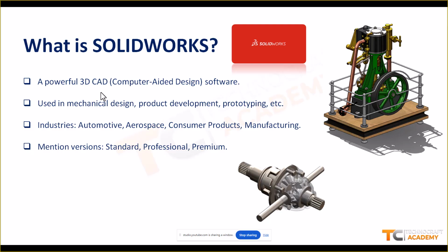When it comes to Standard, you will not get any of the simulation features. You don't have the design library, fasteners, and some other features. You can use the Standard package for normal designing purposes, but we would prefer the Professional if you are running a medium scale industry. If you want to do simulations and everything, we prefer Premium. But in Premium simulation, you can do only static analysis along with a few advanced things.